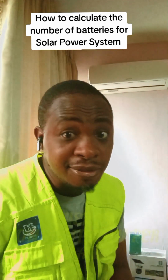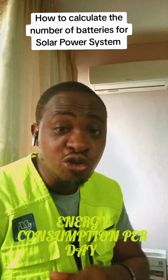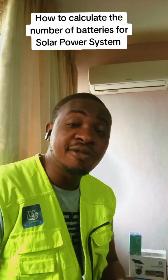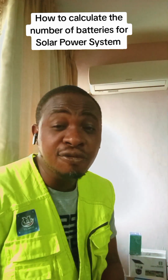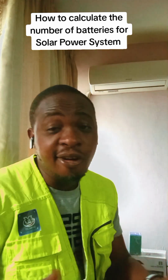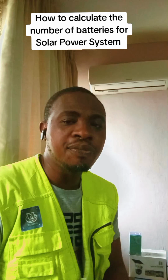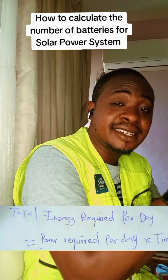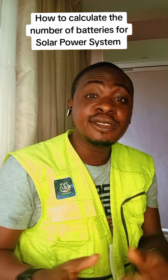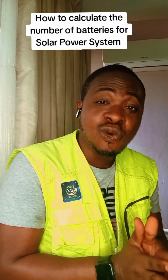So to calculate the number of batteries you need for your project, definitely you need to understand the energy consumption for the day. Sometimes you might want to run your load for 8 hours, or for 10 hours, or for 24 hours, and consider other factors like you not being at home. So you have to multiply the power required by the number of hours, and that gives you the energy required for the day.